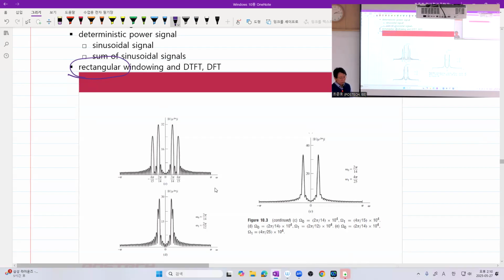So we can increase the resolution very large, which means that we can increase the value of L also very large, which means that we may have very, very narrow main lobe width. But still, using a rectangular window may not be a good choice. By sacrificing a little bit of main lobe width, you may significantly reduce the side lobe height. Especially when you do some radar signal processing, you want to suppress the side lobe.